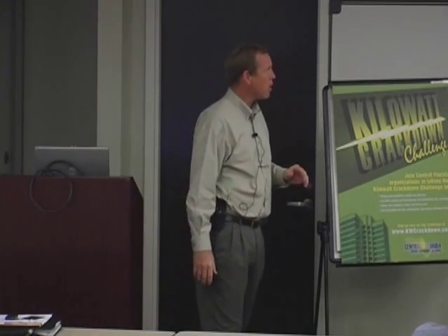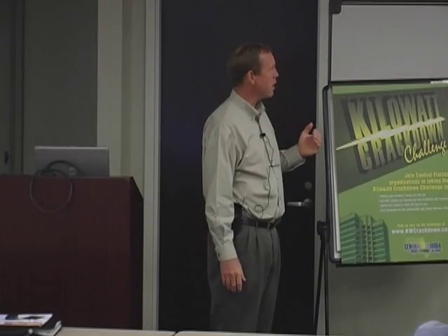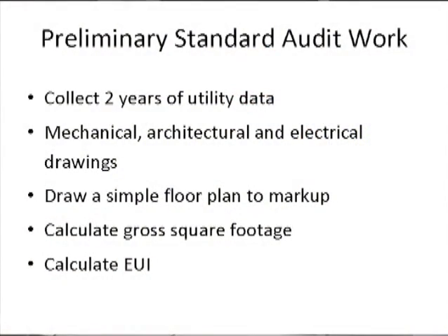Now, preliminary work, I said again, you want to collect 2 years of data, you want to start analyzing that. You want to obtain some kind of drawings of the building. What I like to start with is a floor plan, and I like to make like 10 or 15 copies of that thing before I go out, because I'm going to mark them up.